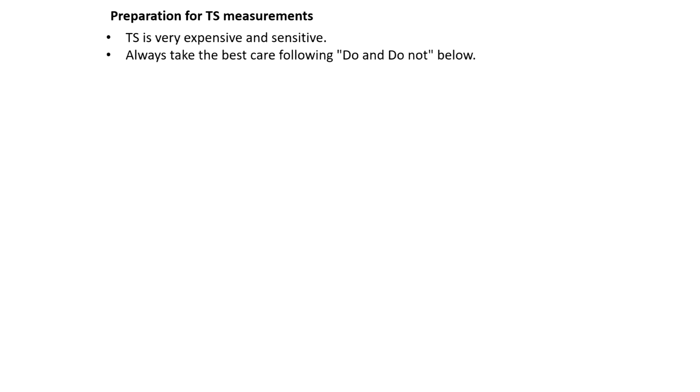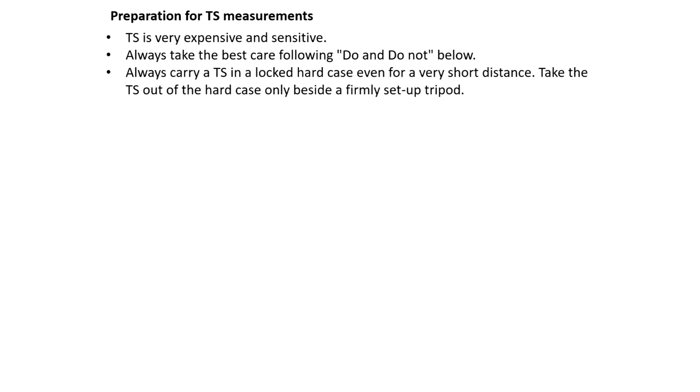So always take the best care, following the do's and don'ts as given below. Always carry the TS in a locked hard case. It comes with that. Take the TS out of the case only beside a firmly set tripod. So this is your tripod. Once the tripod has been set to level, only then you remove your TS from the box.